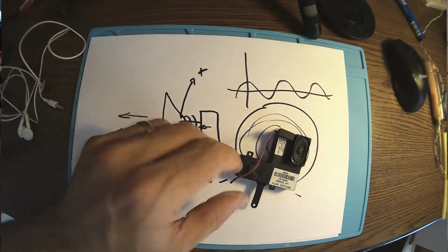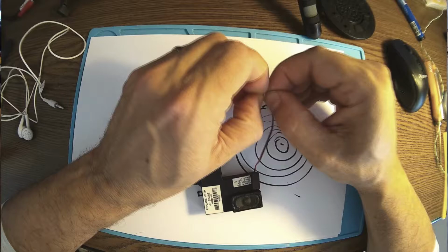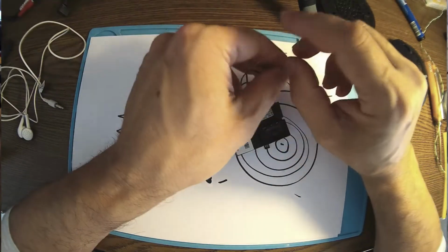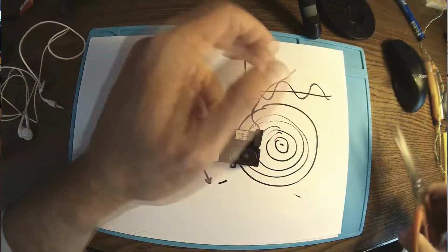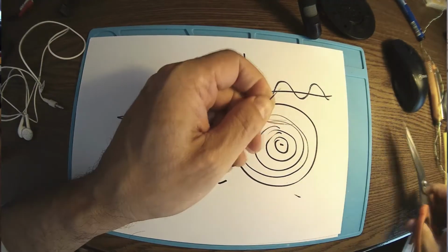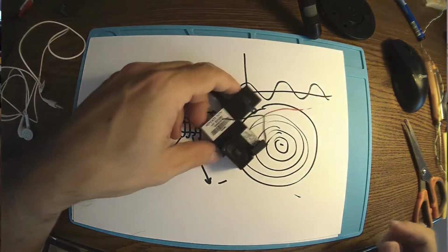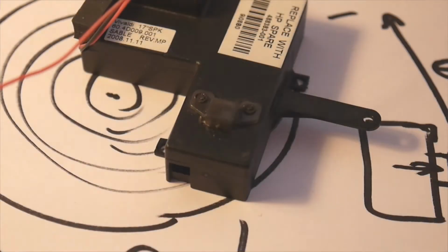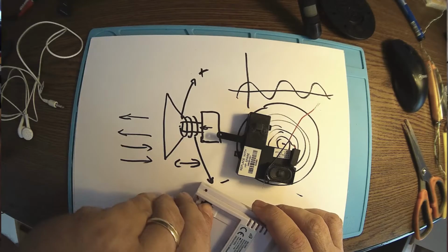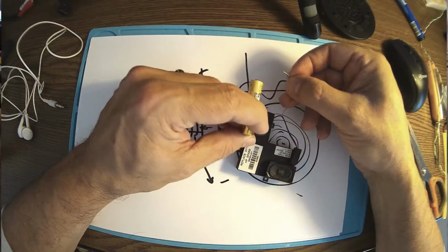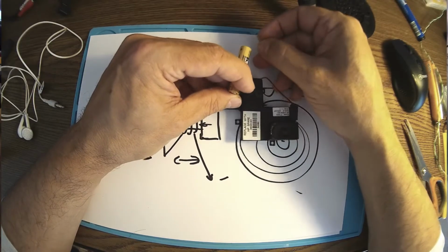If we apply a current to the coil, these are evidently plus and minus from the coil. Usually red is plus. If we don't have any multimeter or testing instruments, ohm meter and stuff like this, you can use a simple battery like this, and if the loudspeaker or the headphones element is okay, then we should hear a beep.